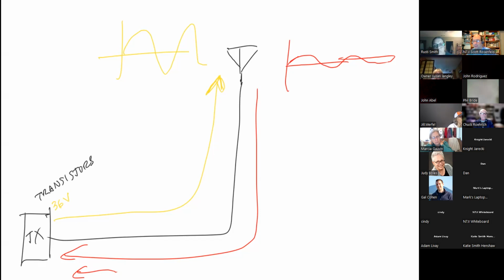If they happen to be lined up, and this is already, let's say, 32 volts, which is legal, within the spec, and this is 12 volts, what happens if they add together? 32 and 12 is 44. And what did we say the maximum transistor voltage was? 36. Kapow! You just blew up your amplifier circuit.